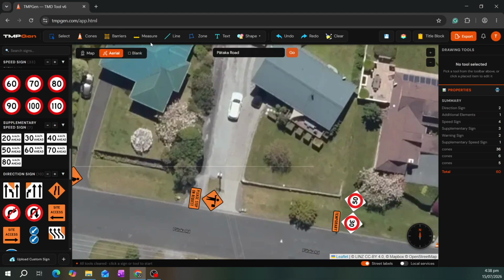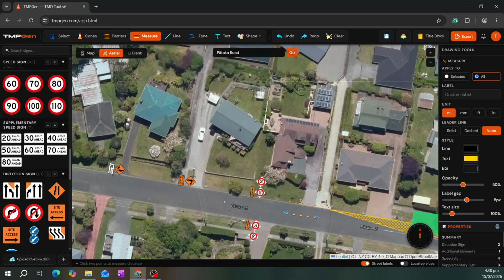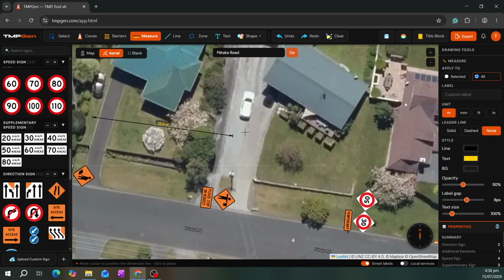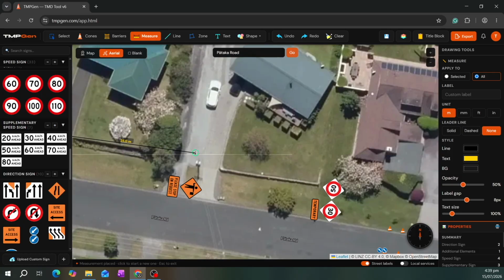Now I'll add the measurements. We know the spacing is 25 meters, so I'll click or type 25 and press spacebar to lock it in. The first click locks that point, and you can then move only vertically. The second click places it wherever you like. For the next measurement, hovering over the edge shows a green circle that snaps automatically when clicked. I'll type 25 again to match.